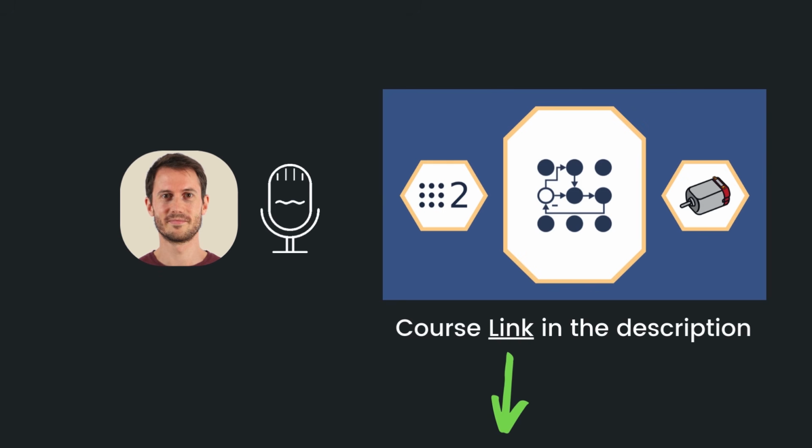Now, if you use ROS2 control, it's probably so that you can control real hardware. And here comes the next step for you. You will need to learn how to create a hardware driver and a hardware interface so that you can bridge the ROS2 controllers with your custom hardware.